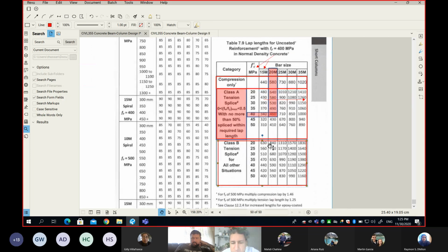Now, here is the point. We said before that this one here is pure axial force, or centric force, with a little bit of eccentricity, which turns your entire section into compression only. This one here is like a beam, which means one side is in compression and the other side is in pure tension, which means the stress in your rebar will become F yield.